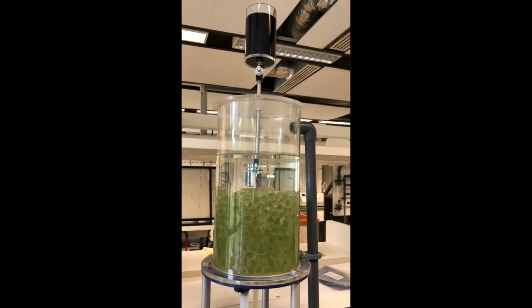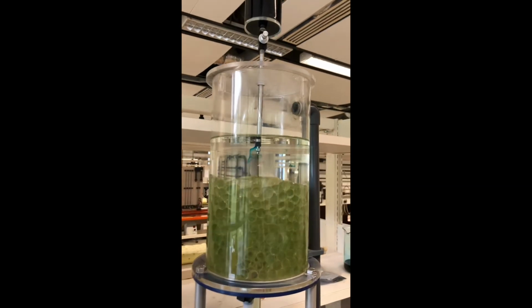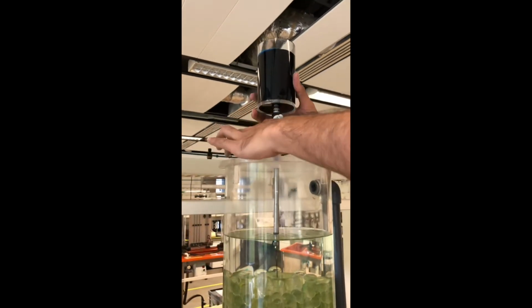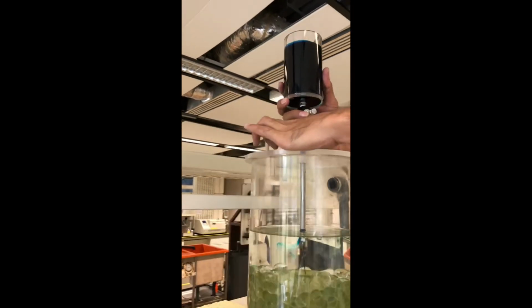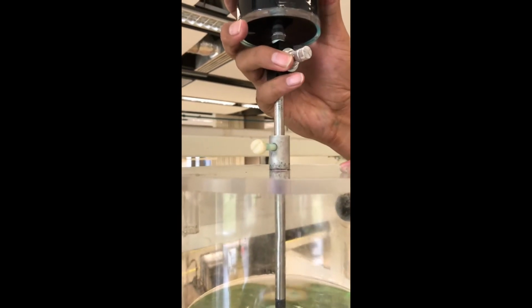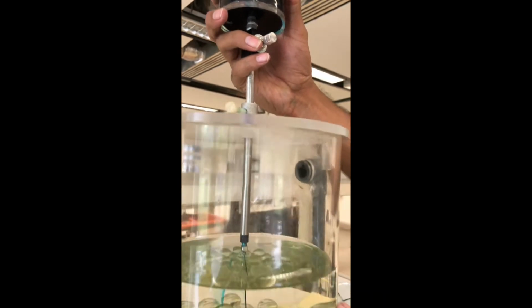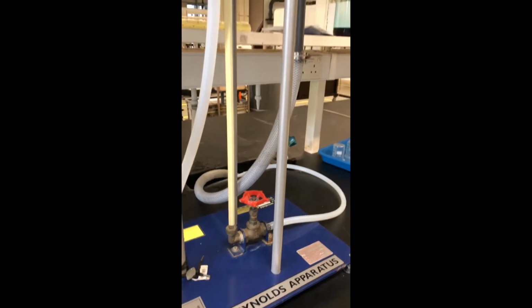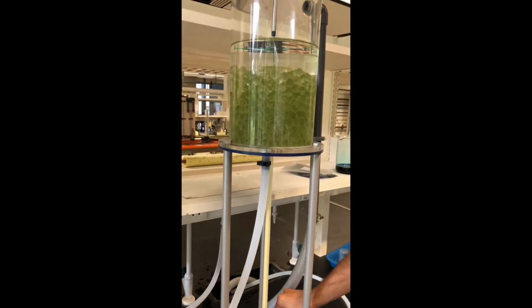We are going to adjust the height of the hypodermic tube using the height adjustment screw just a little bit. Yeah, this is the screw, and we just adjusted the height of the hypodermic tube a little bit. As you can observe, there is a continuous stream of dye coming from the tube, and that can be seen in the test section as well. A continuous straight line of dye coming in the test section.